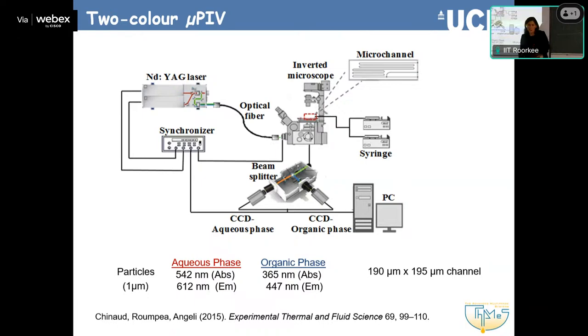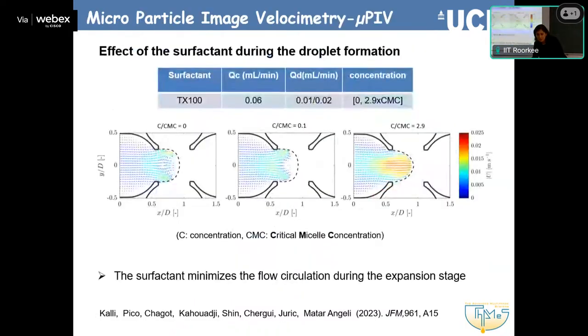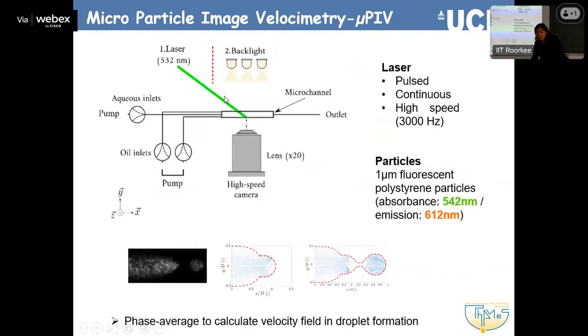When we do PIV, we have one light that is sent to the setup. It's usually a green light. But what the particles emit is a different wavelength. I'll mention it here because this is quite important. The wavelength is different because the camera will have a filter here that completely blocks all the green light and only receives the emitted light, which is usually slightly higher.